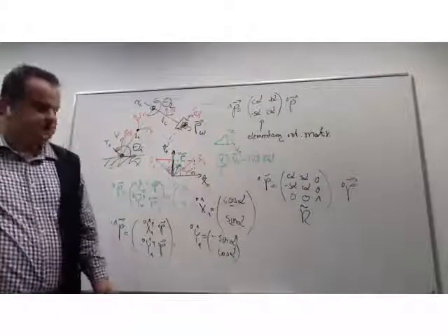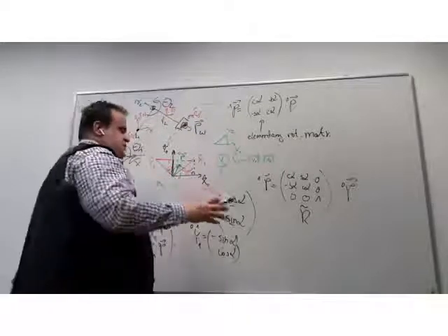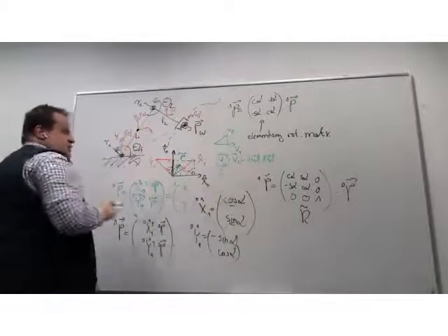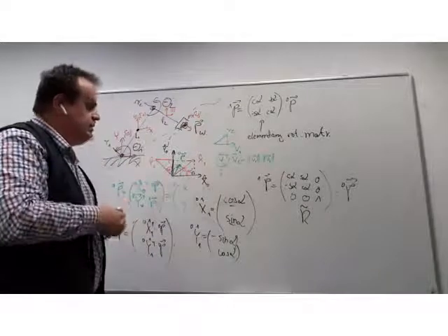So this is basically the transformation which rotates the representation of the point from the first frame to the second frame, which may be rotated due to changing the orientation by θ1.